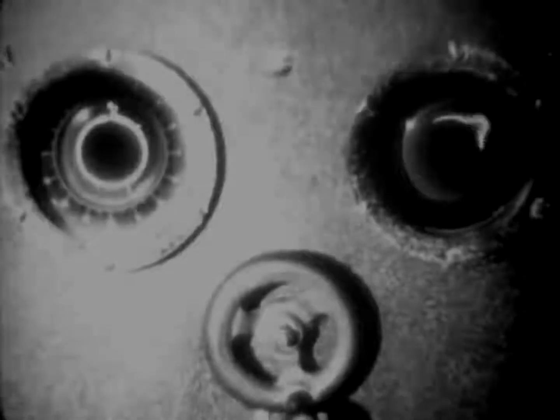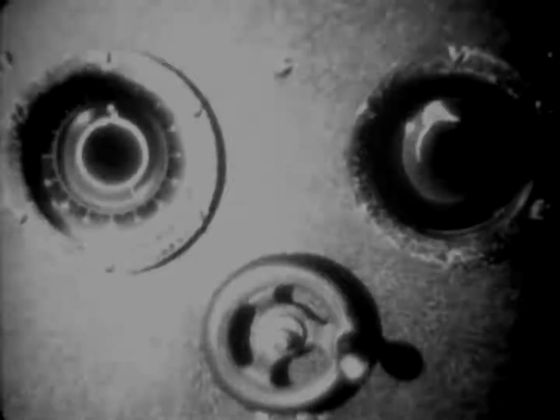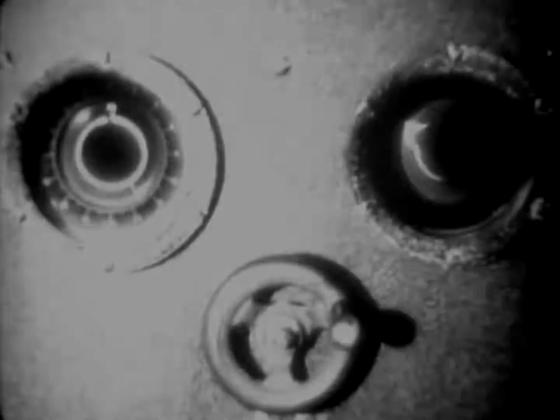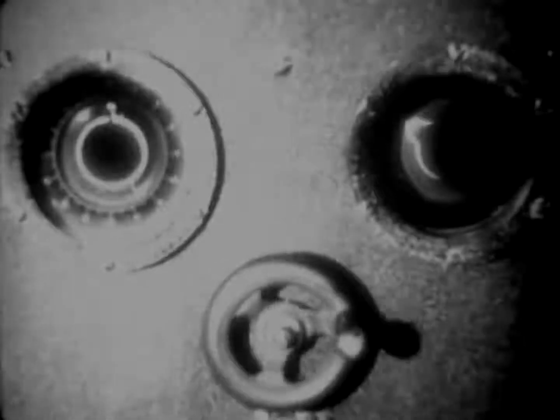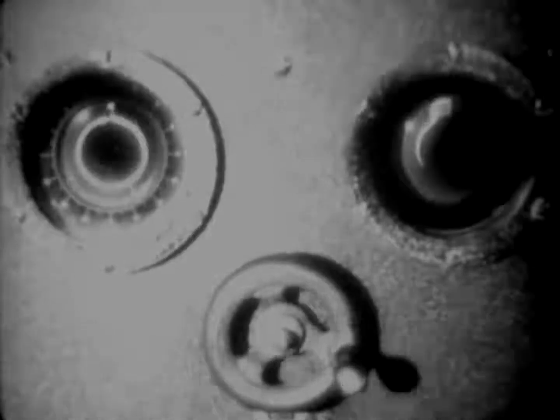To measure range even more accurately, crank this hairline around until it's on the target pip. That makes the echo appear as an expanded pip on the fine range scope, there at the right. It's also a J-scope and shows you an enlarged 2,000-yard segment of the set's entire range. With these 2 scopes, you can locate a target to within a few yards. So much for the J-scope. There was still a need for another type of scope, but before we get into that, let's take a short break.